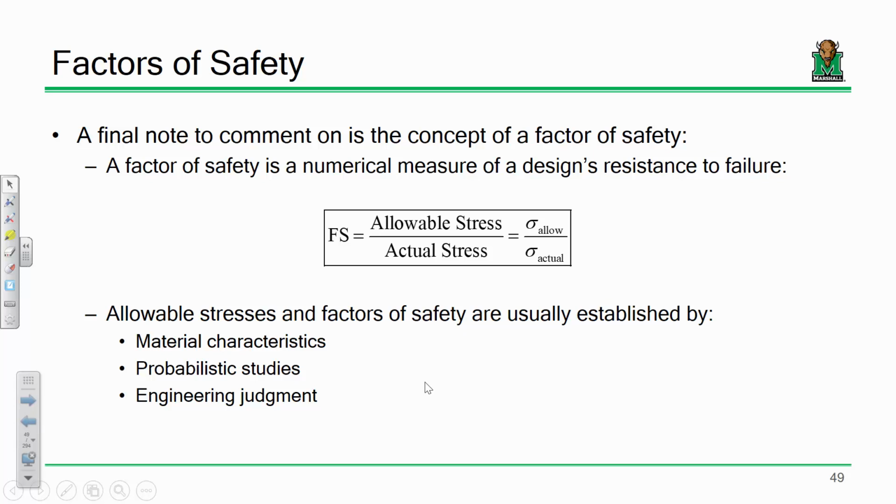So you take its actual stress and its allowable stress and tell me whether or not it's safe, and if so, what's its factor of safety. So that's point one. The second thing that might happen is I might give you a factor of safety, and I might say, okay, if the factor of safety is 1.5, what's the diameter need to be in order to have a safe design? And so that's another instance.